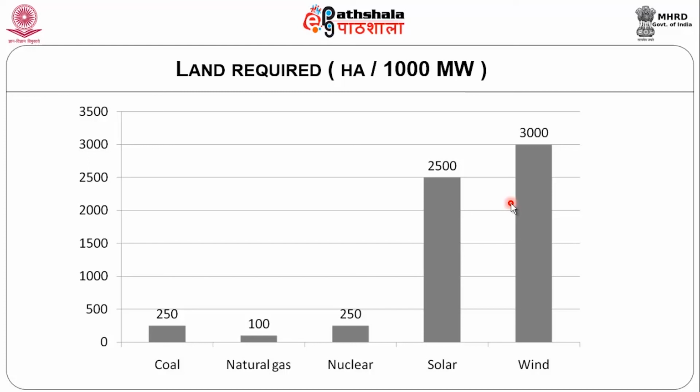If most of the turbines are operated at rated power speed, the performance will be very interesting. Further research is needed to bring down the cut-in speed, which is currently about 4 meters per second. If it is brought down to 3.5 or 3.75, the potential could be increased, and the installations can be increased.